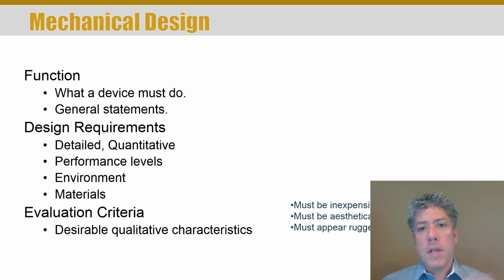Now, I also had a stop in it so that I could have a motor just continuously run with this thing, and the motor would have an overrunning clutch, so not an overrunning clutch, but a friction clutch, so that if a bolt came into position and couldn't get out, the motor would just keep turning, but it would slip.